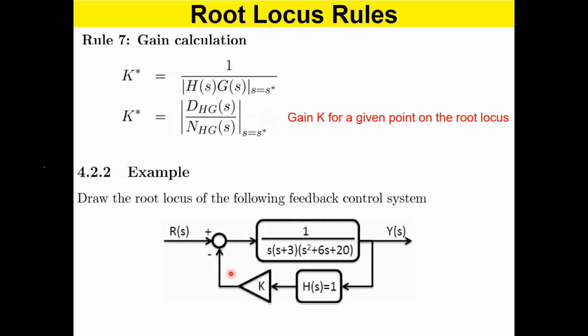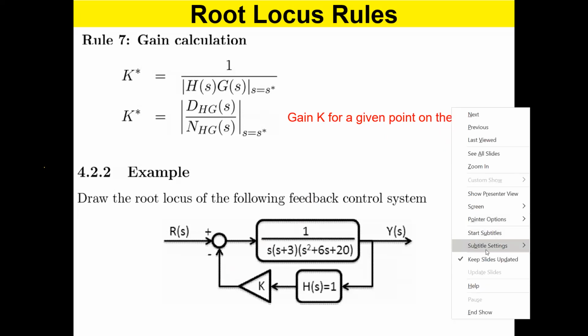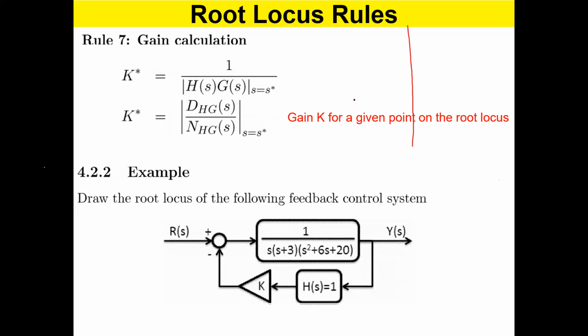And finally, let's say you have your root locus like this. This is your root locus, and you have a pole like this, one pole, another pole like that, right? That's all you have. And as you know, when you increase your gain, this pole goes this way, this pole goes that way, and they meet up somewhere here, right? And after that, one pole goes up, the other one goes down, right? So you know that this is the root locus.